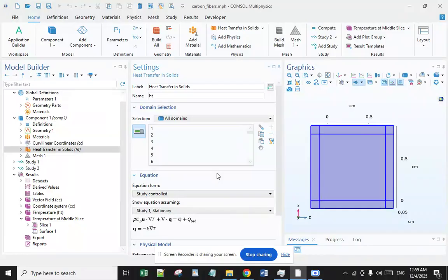It must also be noted that the heat conduction measurements were performed on a single layer of each fabric in direct contact with the flat hot plate and the flat diaphragm, which leaves larger gaps compared to large stacks of fabrics, which would benefit from the nesting of yarns and other microstructural features that would increase the overall number of contact points and contact area between individual fabric layers, yielding higher values of transverse thermal conductivity.